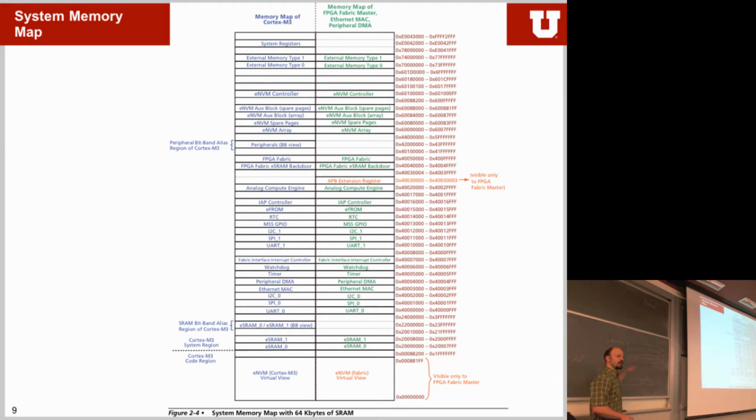So that's a different way of how they oftentimes make access to registers available, without having to go and read the whole status out. The other one is using the bitband area, where you can address individual bits of certain memory locations. Okay? Yes? You mean we have three more registers for every register? 2 more. But that's not always the case. That's just sometimes how they implement, in some peripherals, certain techniques.